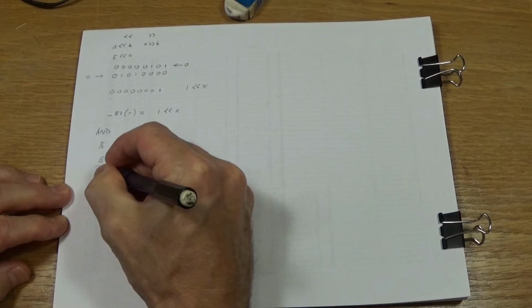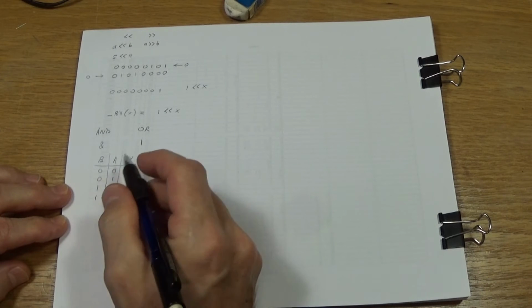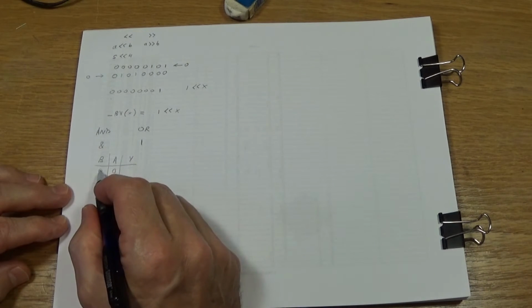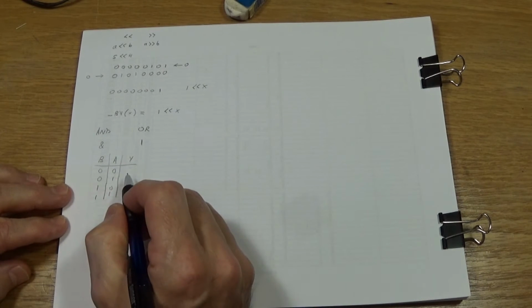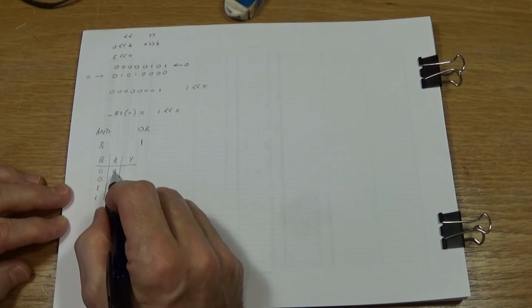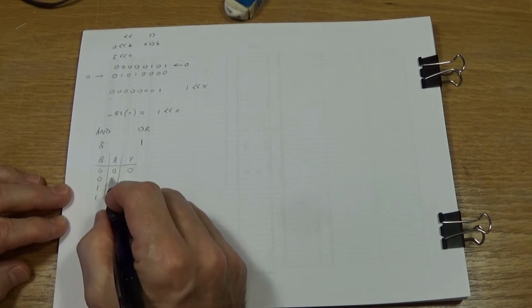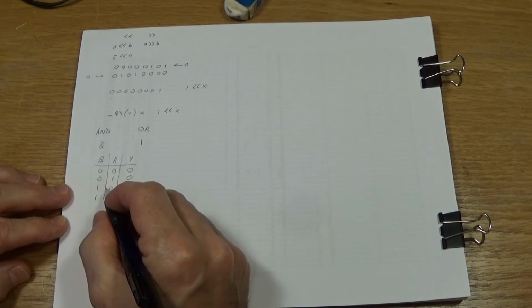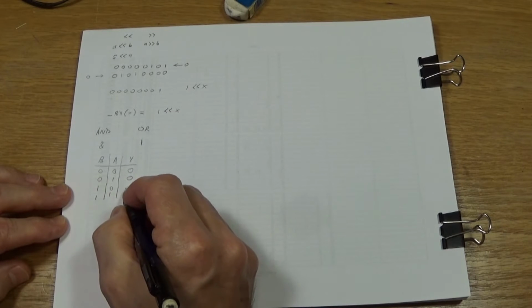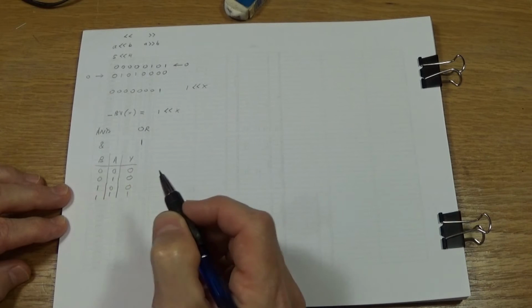I just want to get every combination of bits. And so when you AND, we're going to AND these 2 bits together, A and B. I'm going to do it a bit at a time and I'll give you the result here. So if we AND a 0 and a 0, the result will be a 0. If we AND a 0 and a 1, the result is still 0. And if we AND a 1 and a 0, the result is still 0. If we AND a 1 and a 1, the result is 1.